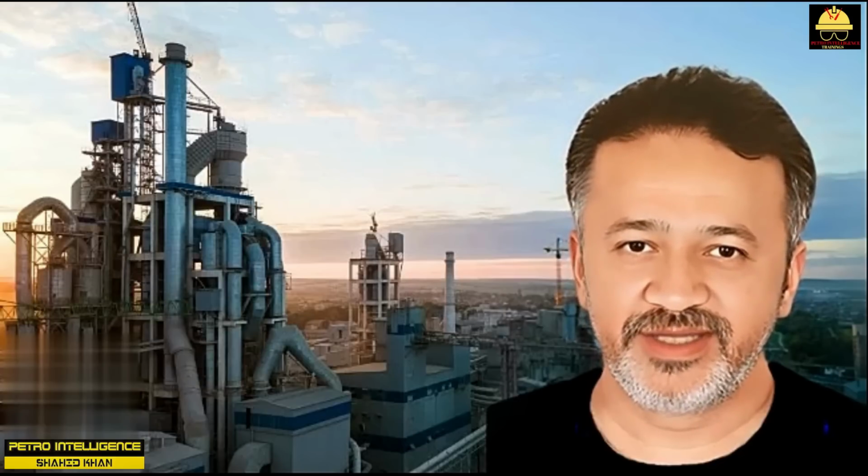These steps reduced the steam generator pressure from 170 to 150 psi and increased the pump-around gas oil inlet pressure from 140 to 160 psi. He then checked the blowdown drain on the steam generator and found it to be contaminated with the greenish gas oil. This proved that the steam generator was indeed leaking. Incidentally, there were no tube leaks. The leaks were where the tubes were rolled into the tube sheet. These are called roll leaks.